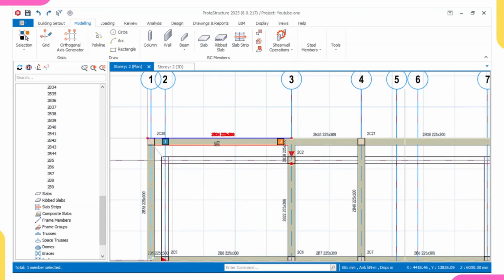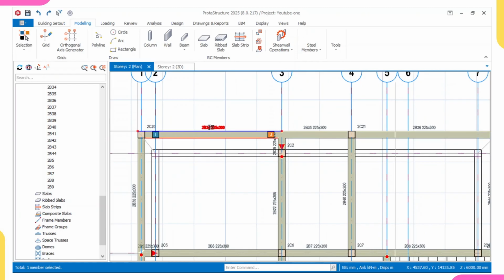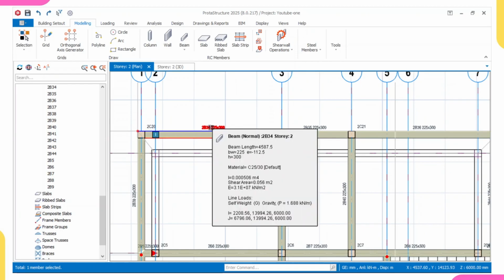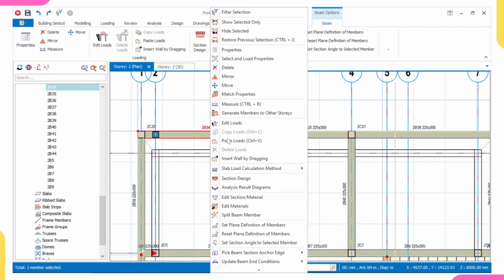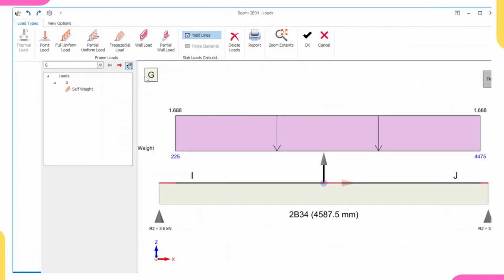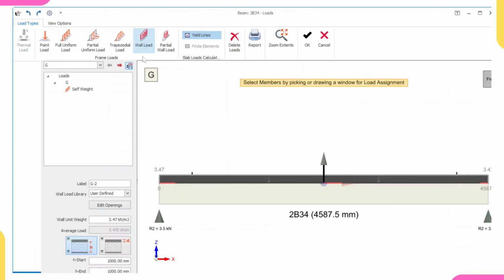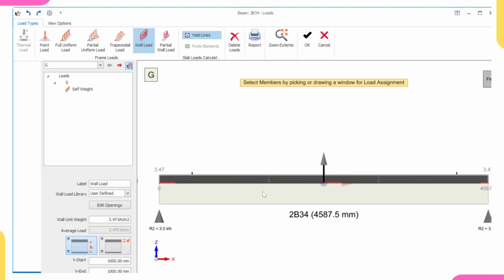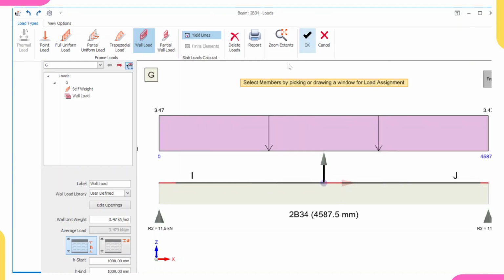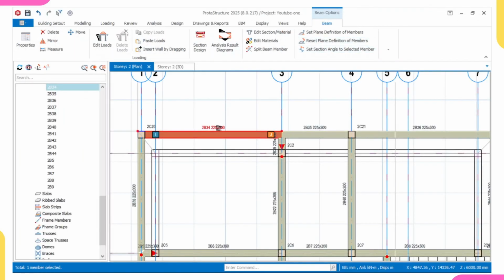Okay, in fact, let's do the one of parapet load. Let's just apply a block wall of height 1 meter. So you see that also after design that it will still pass. So let's just apply it. I'll click on it, then right click, and go to edit load. Once this dialog box appears, I'll come to wall load and change my wall height to 1 meter. I'll then click on OK. Yes, so I've applied this.